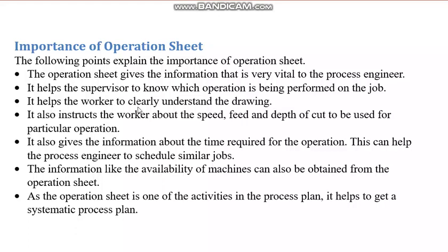Okay, you see, it helps the worker also to clearly understand the drawing, because drawing itself is not giving all the information. The operation sheet will give vital information. Then it also instructs the worker about the speed, feed, depth of cut, these process parameters which he is going to use for the operations.